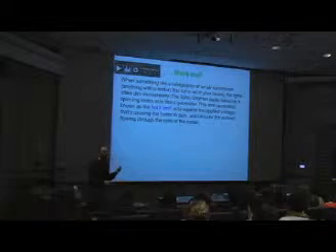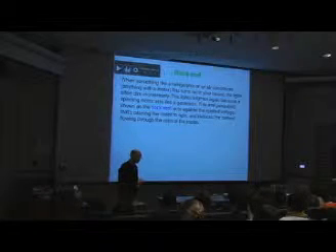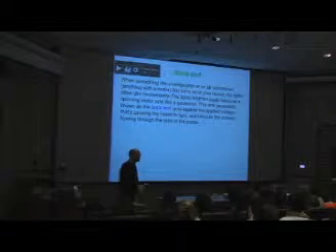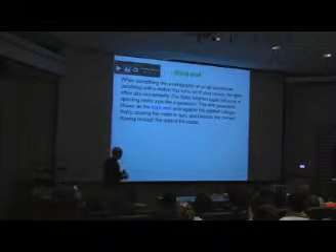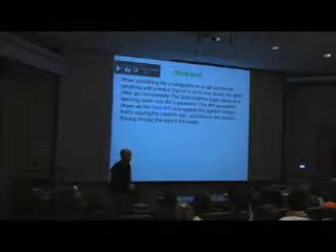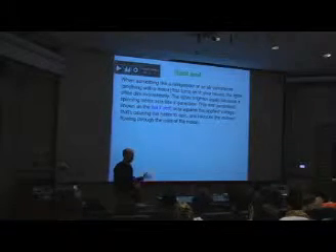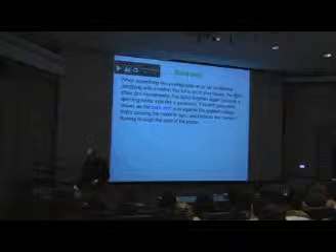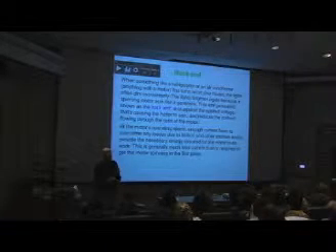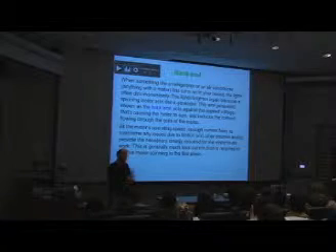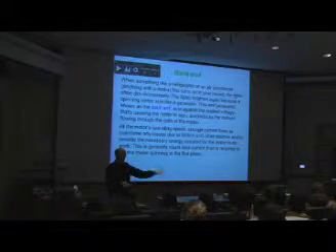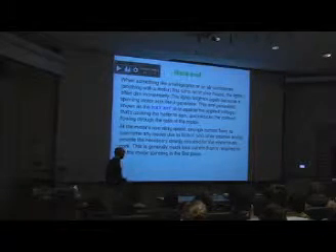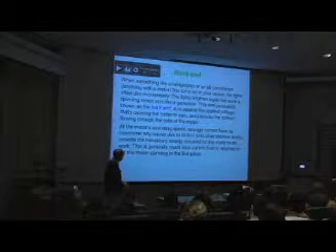And that generated voltage always opposes the voltage that's trying to make the thing spin in the first place. This is why we call it a back EMF, a voltage that acts against the thing that's making the motor spin in the first place. And because these voltages are basically in opposite polarities, you get a reduced current. It's like having two batteries, one hooked one way, one the other way, and the current overall is reduced. So at the very beginning, when the motor first turns on, you don't have any of this back EMF because the thing's not spinning. So you draw an incredible amount of current. And then when you get it up to operating speed, you have much less current because of this voltage generated by the motor itself.